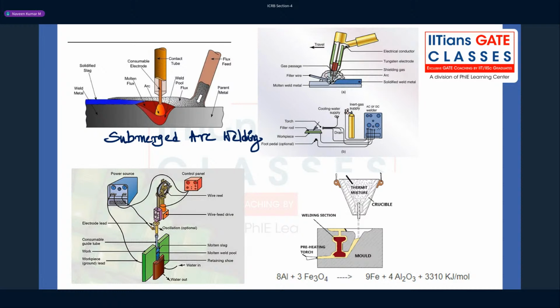What is the submerged arc welding? The submerged arc welding is nothing but a weld metal, and you have, can you see here? This is some kind of a flux, powdered flux that is placed beforehand, and the arc is submerged inside this flux, right?